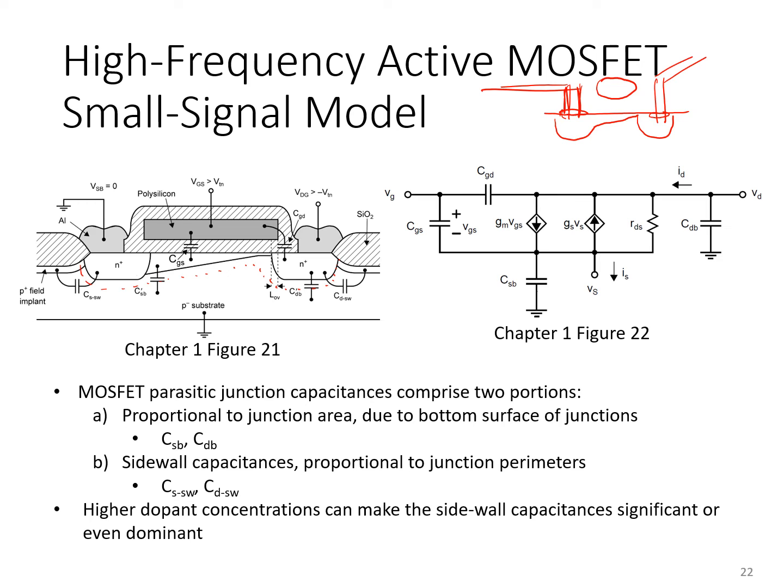And so now you can imagine that there are parasitic capacitances arising all over the place, essentially everywhere you have two closely spaced conductors. So between the gate and the contacts, there are also contacts to the gate required, connecting it to other metal wires. And now between metal wires, you may see additional capacitances.